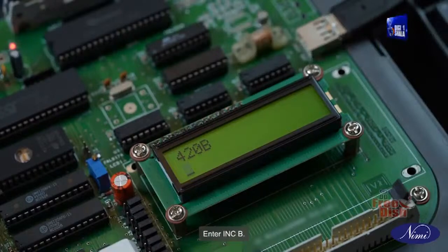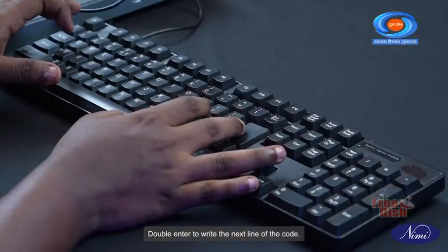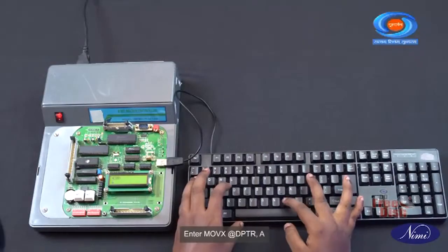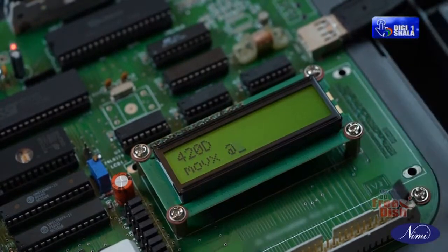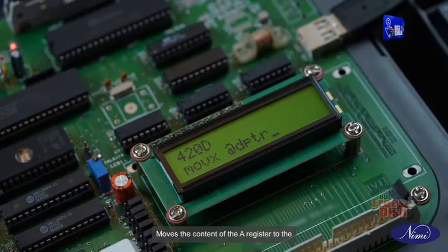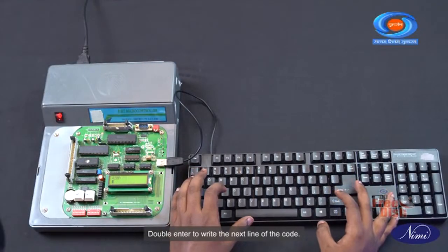Enter INC B. This increments the register B by 1 when the carry flag is set. Double enter to write the next line of the code. Enter MOVX @DPTR, A. Moves the content of the A register to the external memory address. Double enter to write the next line of the code.